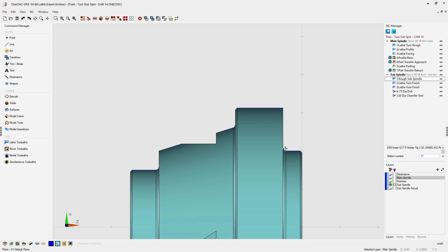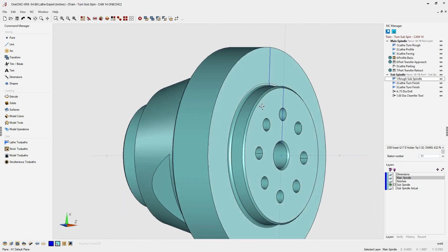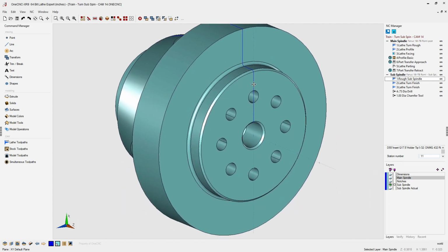All right, very good. Now that we've taken care of that, let's take a look at creating the geometry for these 8 holes. For good housekeeping, I think we should create a layer for this. So I'm going to head down to the layer browser. I'm going to right-hand mouse click and select Add a Layer. Now this is something you don't have to do. Again, I think this is just good housekeeping. For the layer, let's rename this by double-clicking on the layer name. And why don't we call this 8 holes on face? That looks good, so I'll click OK to that.